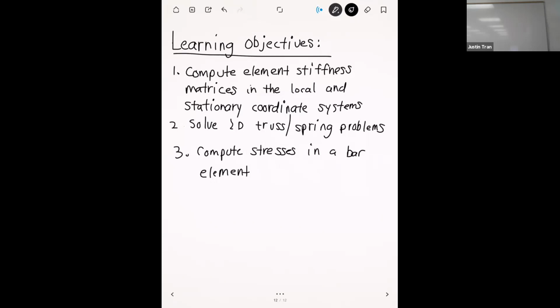I ended up doing a pressure of 1 PSI in the middle. Is that kind of appropriate? I think I ended up with an equivalent stress of about 315, so a little bit less than the yield strength. Okay. Thank you very much. Yep.